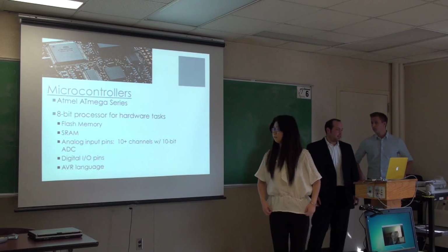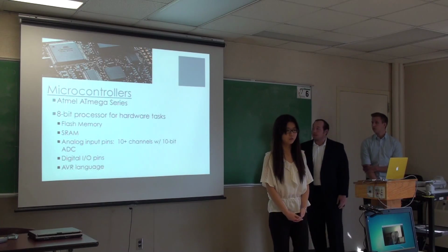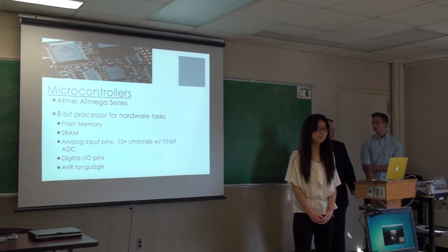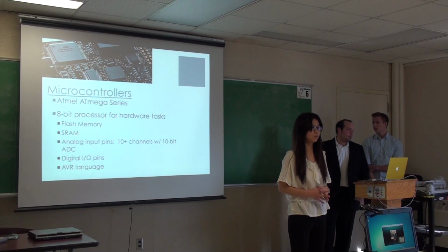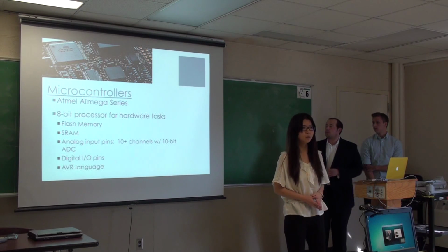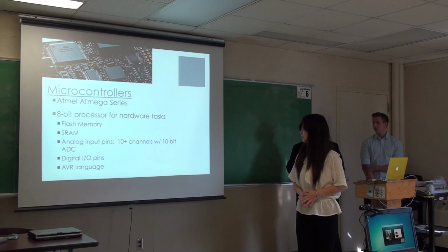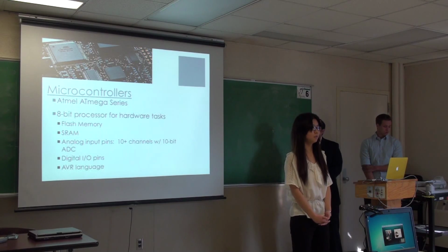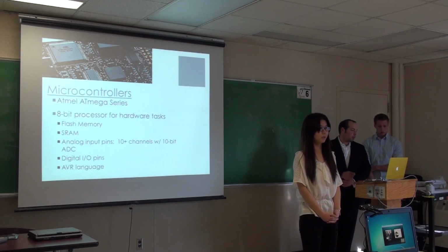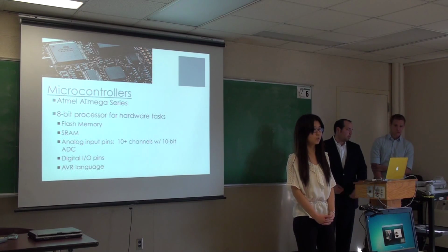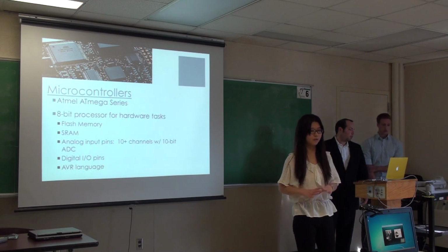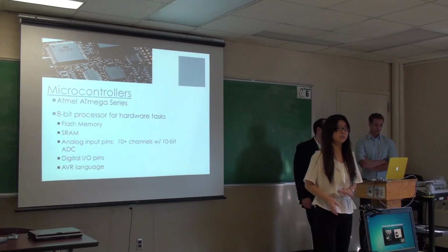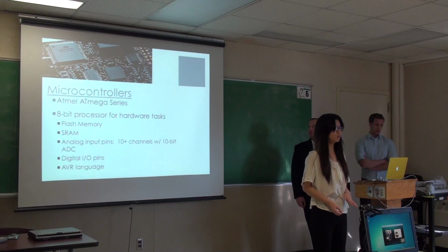So the microcontrollers used in the Arduino platform, like in other boards, use the same family of chips called the Atmel ATmega series microcontrollers. They are 8-bit processors, meaning that they can access 8 bits of data in a single machine-level command, and their data bus is 8 bits wide.